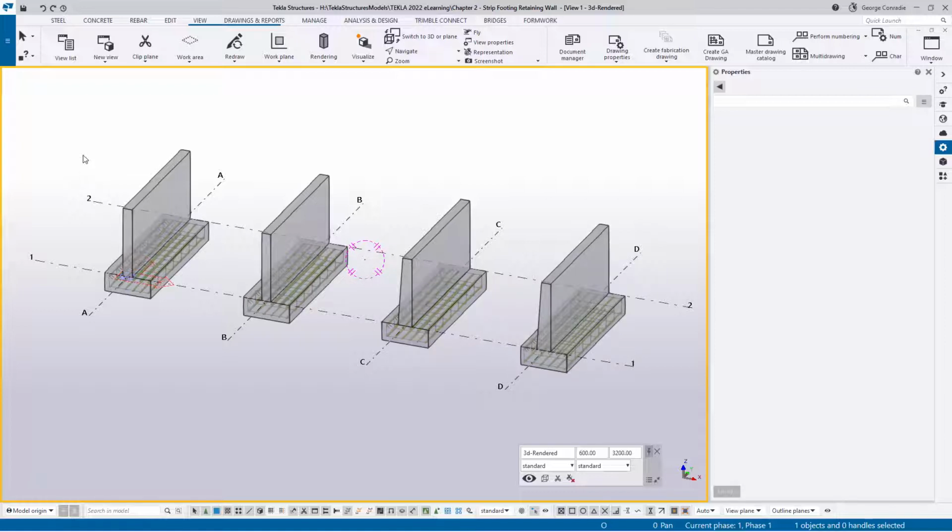Now, what I want to do is manually reinforce this wall as a rebar group. And then I want to do the equivalent as a rebar set so we can see the difference, and the benefit of using rebar sets over rebar groups just by detailing walls, and then also do similar for the tapers. It's going to be a very similar exercise except the tapers have a slight difference to it.